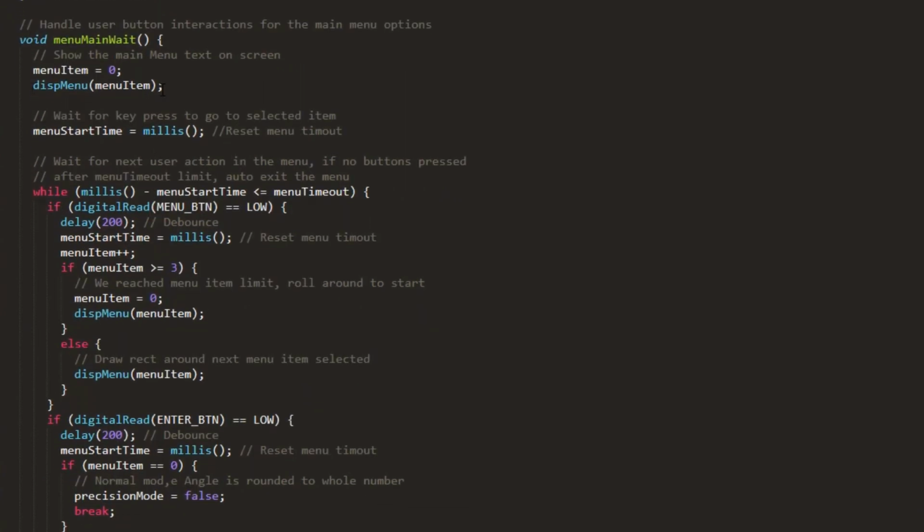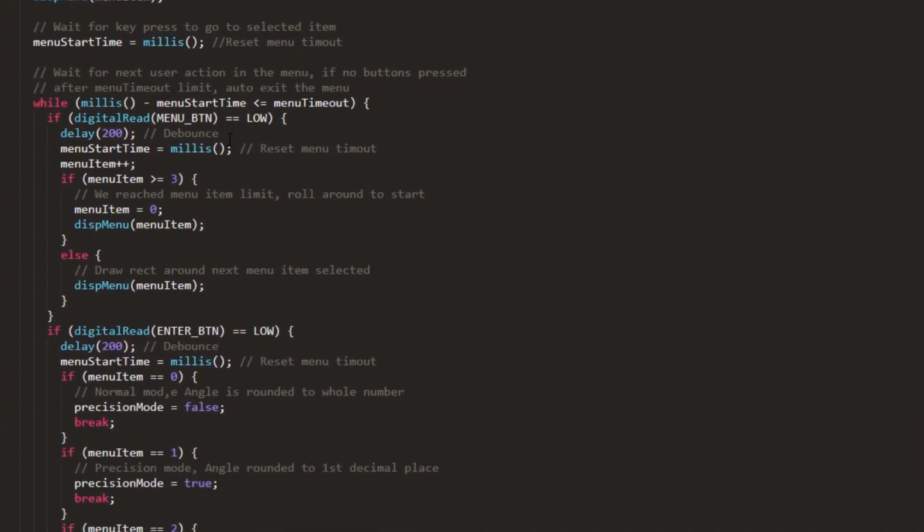We've now shown the menu on the screen and we kick off the timer. So we capture what the current Arduino Nano timestamp is with millis, and we start to then loop through this piece here. If we haven't yet approached the timeout period, then the display will sit there on the screen, or the user is pressing buttons which will constantly reset that timeout.